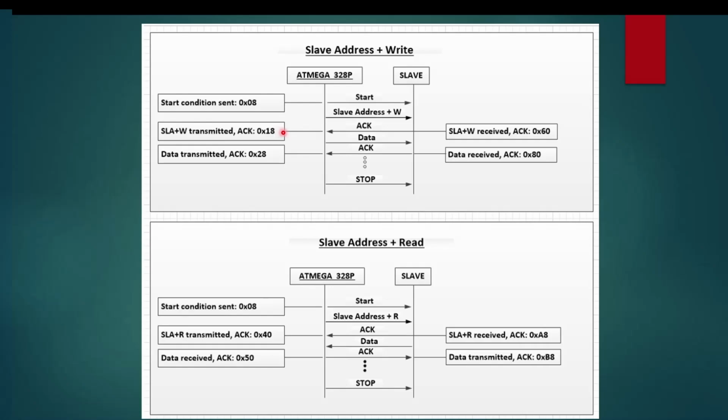After that, the master is going to start sending data. Every time it sends data, it's going to monitor the status code until it gets a code 28 hex. At that point, it knows that the data was transmitted successfully and acknowledgement was received. It's going to continue to do this until it has transmitted all the data, at which point it's going to send the stop command, which releases the bus.